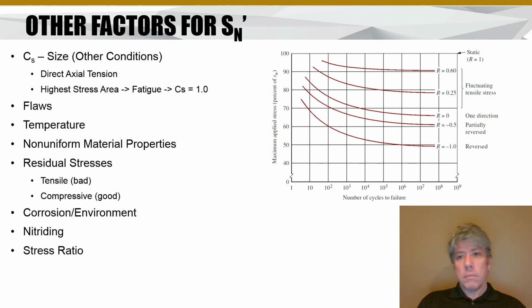But you know, we're not too far off. As we go down to R's that are lower and lower, what's happening is the minimum stress is going lower and lower by comparison to the maximum stress. And we're getting lower numbers till we finally get to the point where we have just R equals 0, and in that case what we've got is a pulsating stress, right, where the minimum stress is 0, the maximum stress is some tensile stress, so we get just 0 from that.